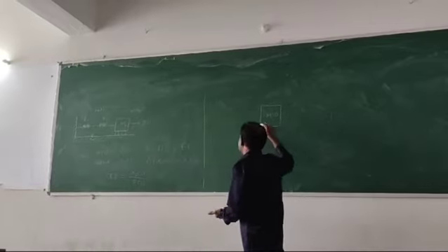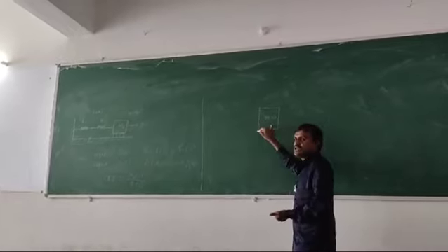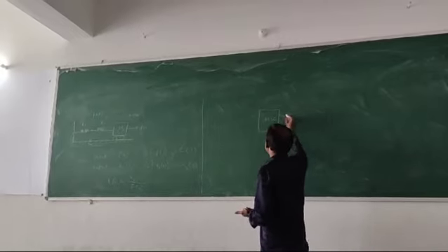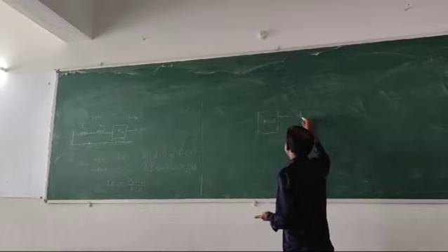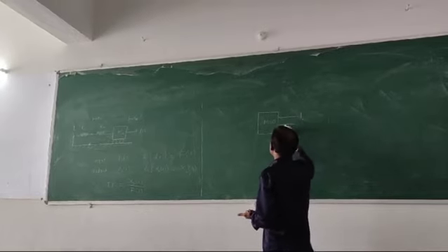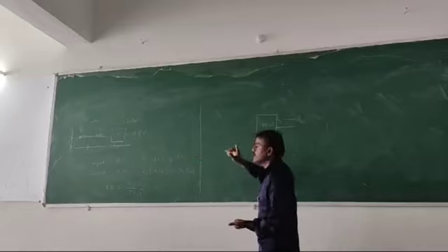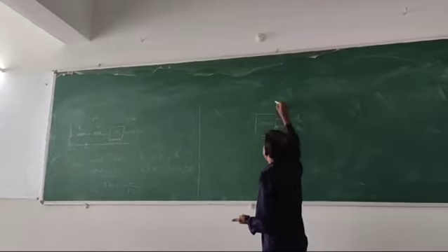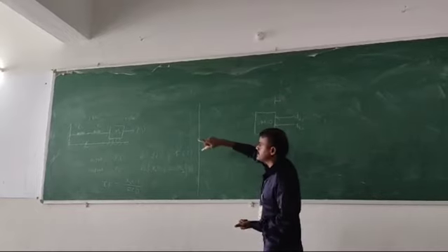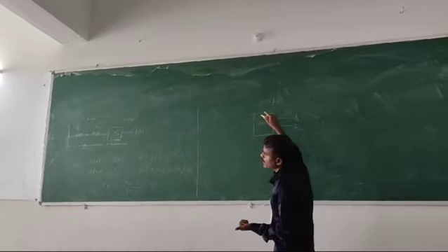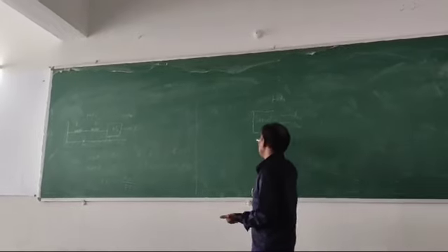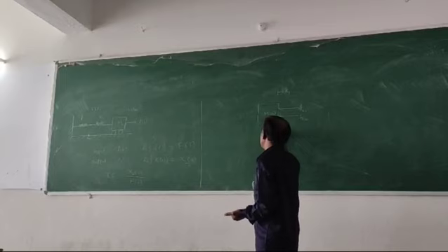Because of those two elements, opposing force will be applied on this particular mass. That opposing force is represented as F(K1), the opposing force offered by spring K1, and F(K2), the opposing force offered by spring K2, and the displacement of this particular mass is x1. So now this is called the free body diagram.